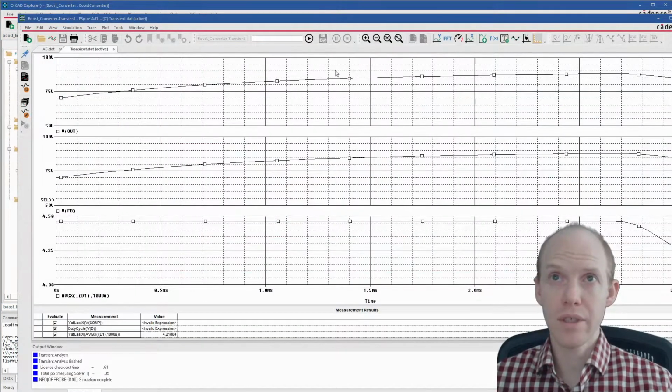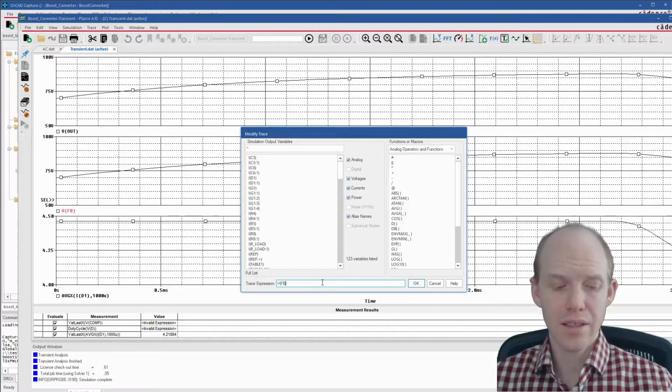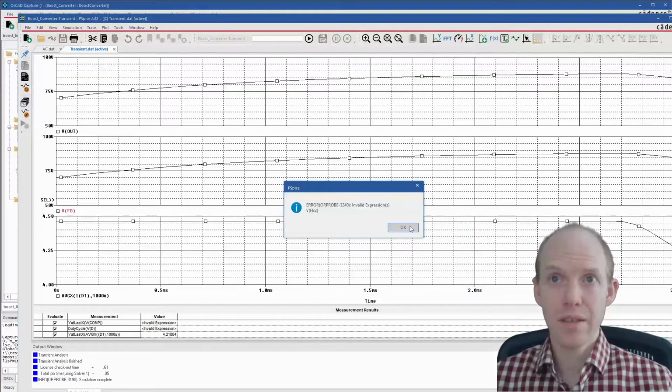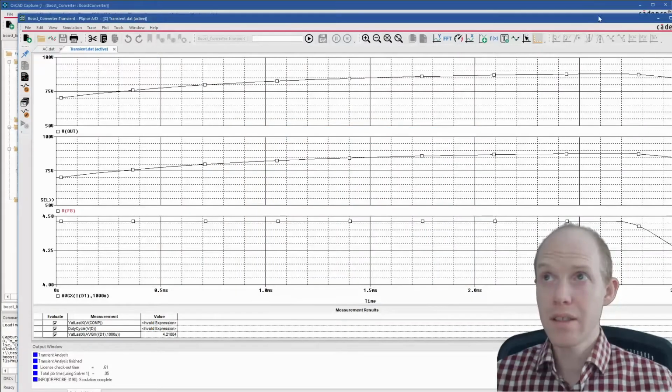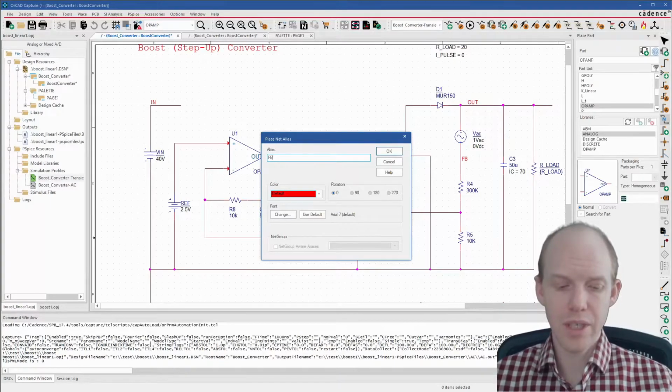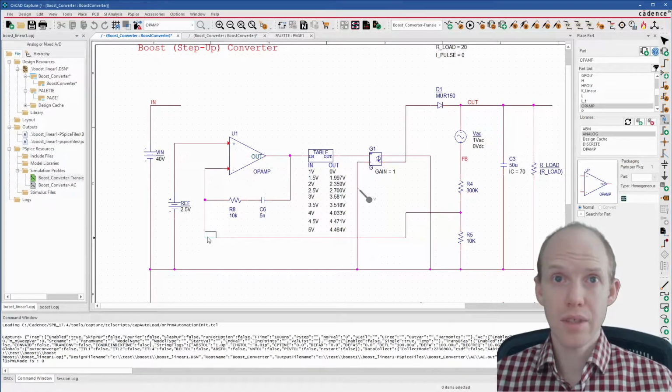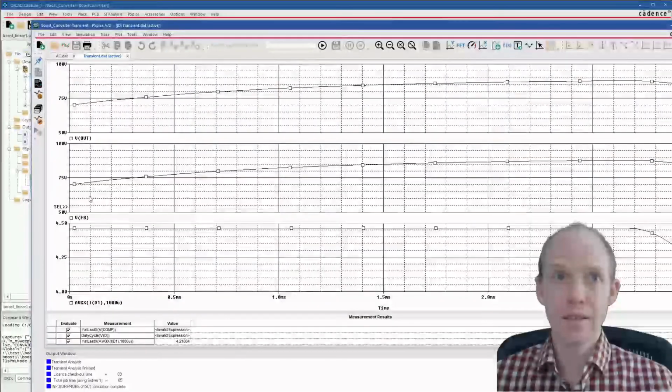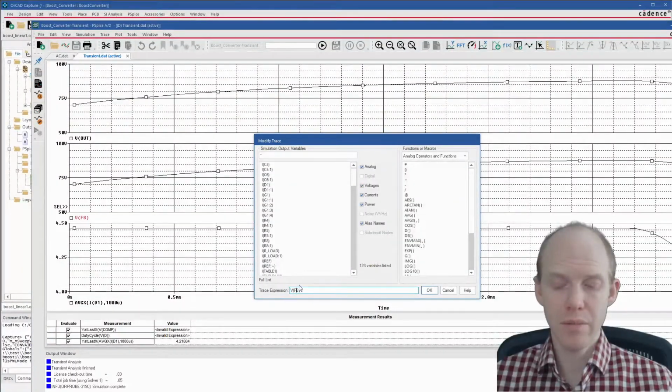So that one looks a little bit interesting, but it's not exactly reaching steady state at the 75 volts, and this feedback is really crazy. The feedback is showing 75 volts. That's because this here should actually be feedback 2 now, although I think we forgot to include that, so we're going to have to do feedback 2, put that one here, run that again, and this guy here should be feedback 2 now.